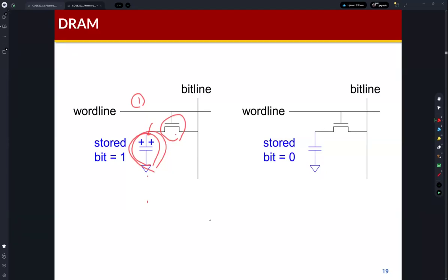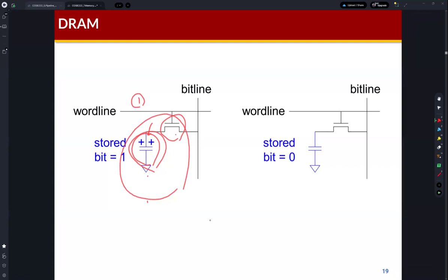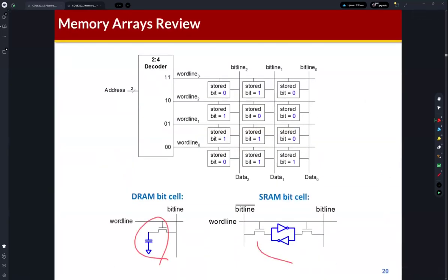So that's why DRAM is slower than SRAM, right? Because it depends on the signal strength. So this is kind of an analog circuit design issue, right? But the circuit is different. So you can just understand the circuit is different. Okay, so in a DRAM, the strength is low, so it takes a longer time to fill this capacitor. Okay, that's why DRAM is slow. Also, it's unstable. Okay, so DRAM looks like this. So only this part is different.